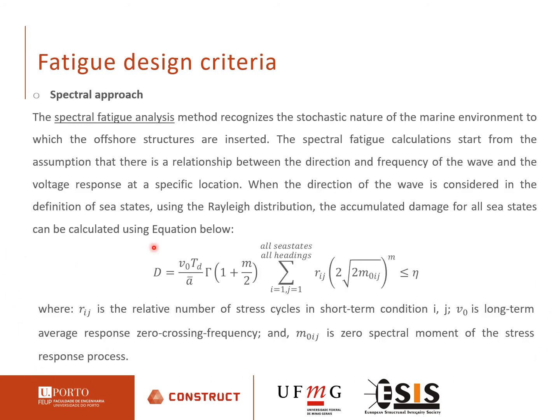Due to the excessive sensitivity of the estimated fatigue damage to the Weibull parameters, a spectral fatigue assessment becomes more popular for offshore structural analysis. The spectral fatigue analysis method recognizes the stochastic nature of the marine environment to which the offshore structures are exposed.